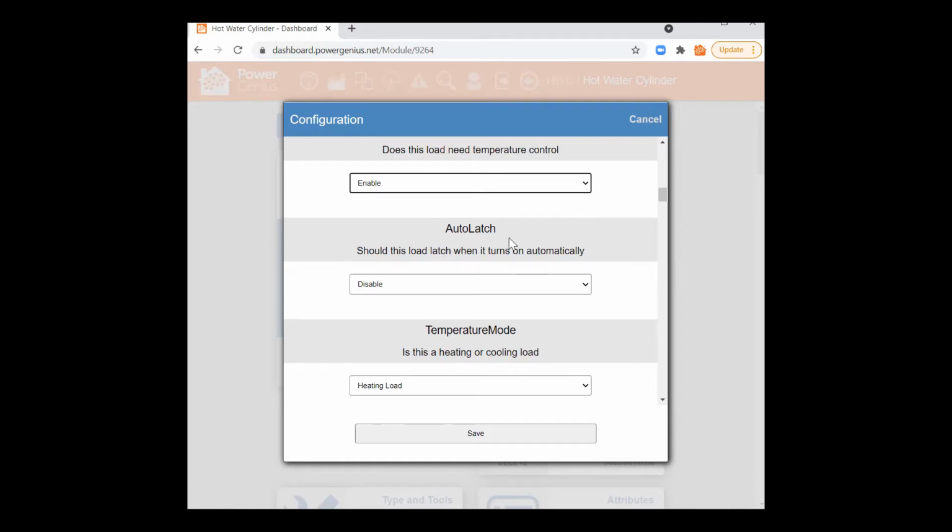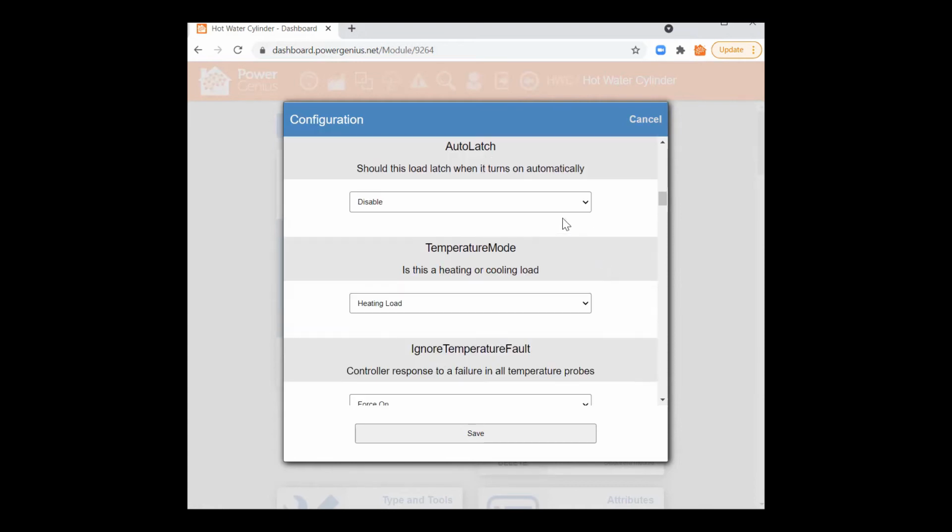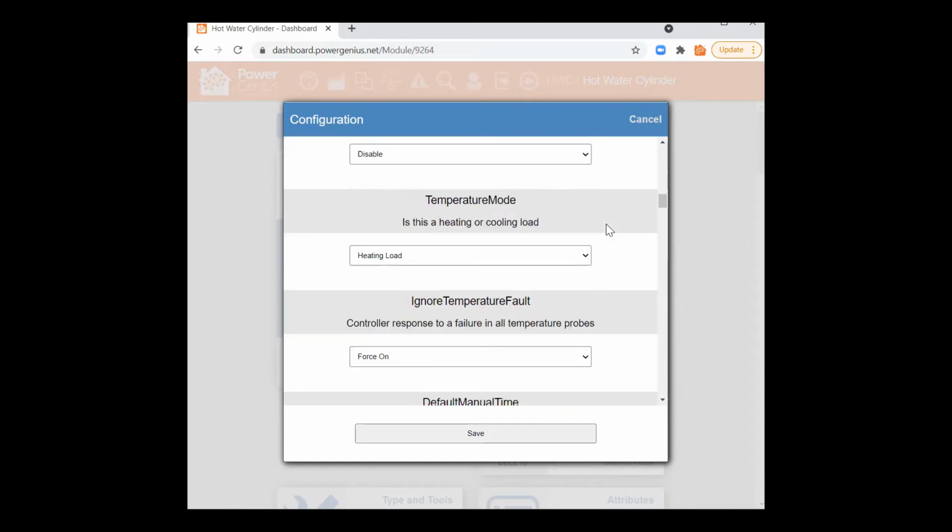What else this does is it's designed for a dishwasher or a washing machine specifically, or any device that once you turn it on, you want the thing to stay on and complete the load. So what else it does is when you power cycle the controller, it will come back on in auto off mode. So basically there'll be no power on the appliance, but the controller will be waiting for an on signal. And that might be export, it might be cascading, it might be a timed signal, could be anything, but the appliance is off. More explaining on that later, different video.